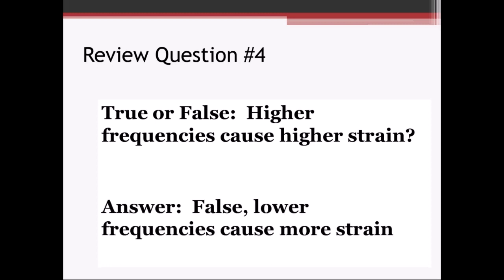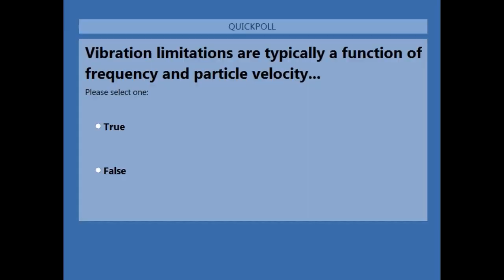True or false, high frequencies cause higher strain. That's false. Lower frequencies cause more strain. And last question, true or false, vibration limitations are typically a function of frequency and particle velocity. That answer is true. That's the reason for that stair step nature in those vibration threshold documents or charts.